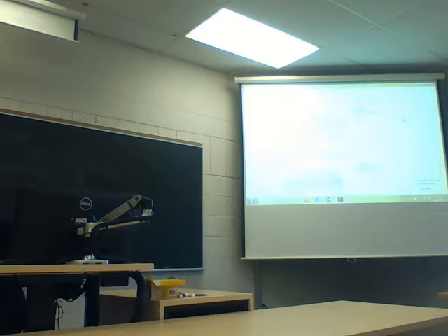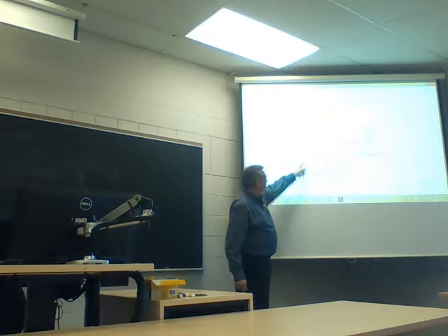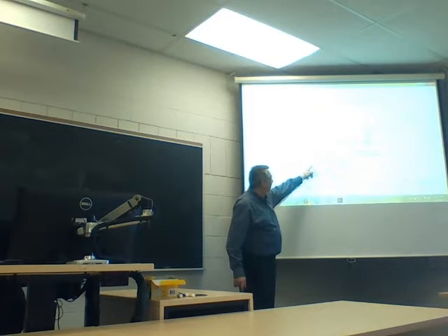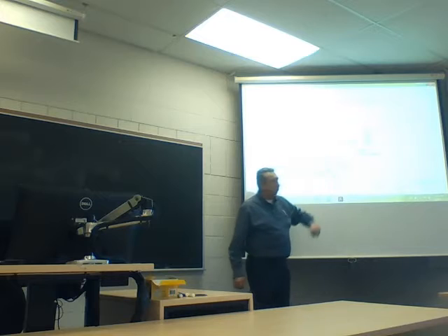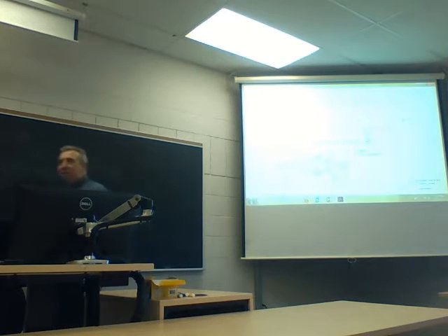Look at that beautiful thing. Oh, it's a terrible picture. So these ones are mounted to the rotor, these ones to the casing. One stage, two stage, three stage, four stage, five stage, six stage, seven stage, eight stage. So that's what they're talking about, an axial flow compressor, just like a turbine. Jet engines and gas turbines use the axial flow compressor.